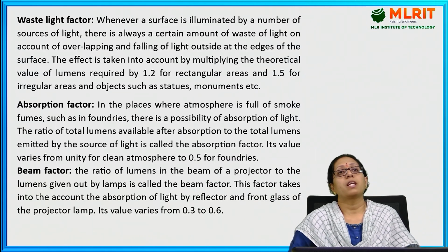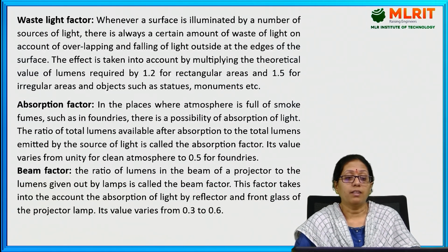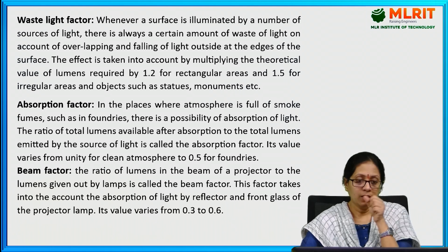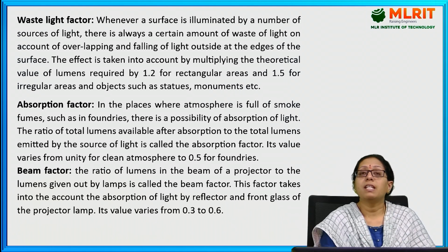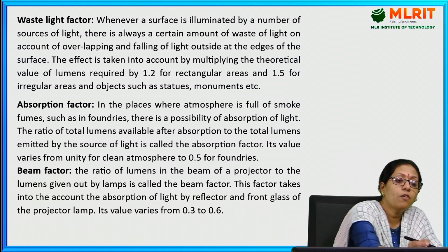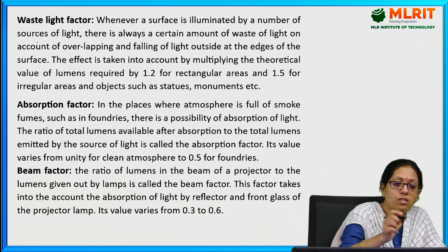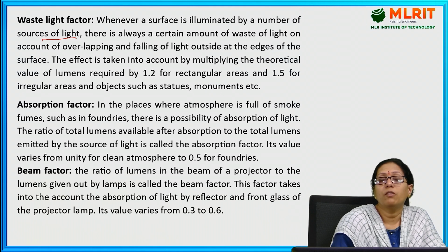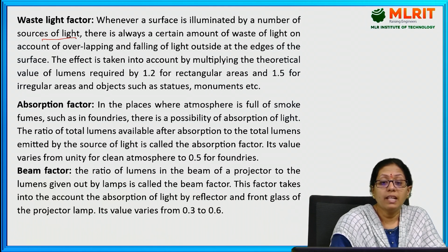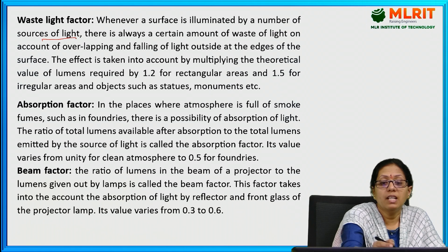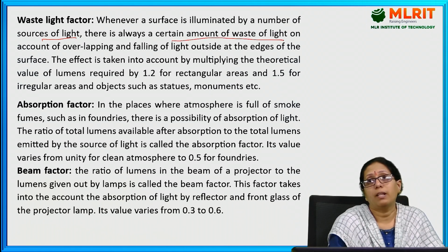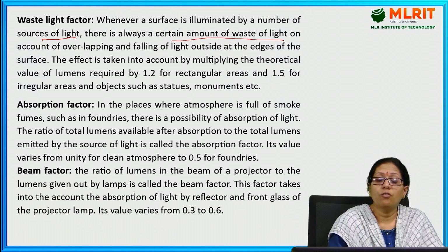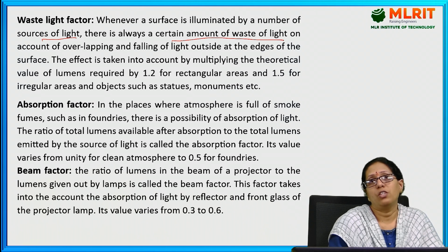So next one is waste light factor. Whenever a surface is illuminated by a number of sources of light, that means in a particular room if there are a number of lights, there is always a certain amount of waste of light on account of overlapping and falling of the light outside of the edges.